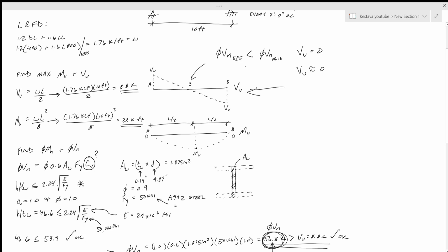So, rule of thumb, if the contractor wanted to put his penetration on the ends, that's when we'd worry much more about our shear capacity, and subsequently we'd worry a lot less about our moment capacity, because our ultimate moment is greatest at the center line of the beam at midspan. So that's where we're going to take the biggest hit. So we need to definitely check our moment.